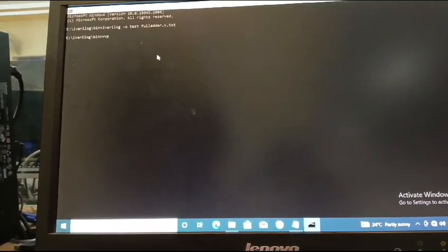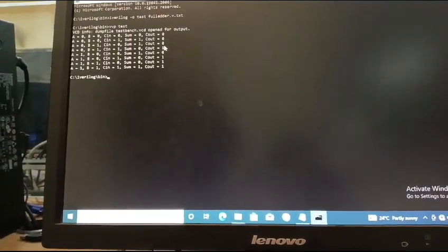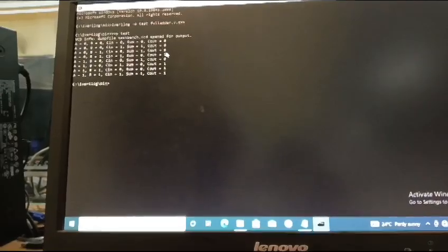To see the output we have to use the command vvp and the object which we used to see the output, here test. This is the output of the full adder. Let's see the output in GTKWave. For that we have to use the command gtkwave space test bench name .vcd.